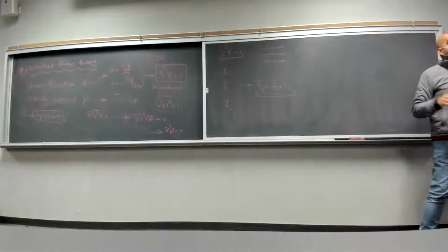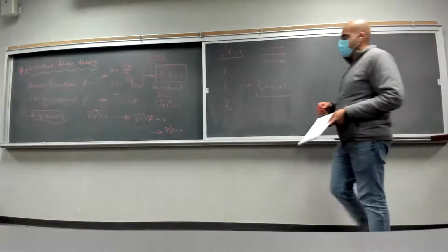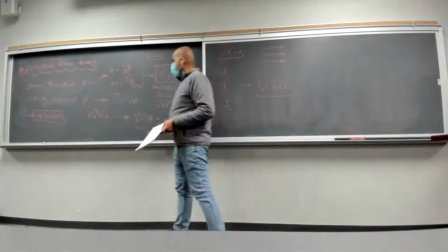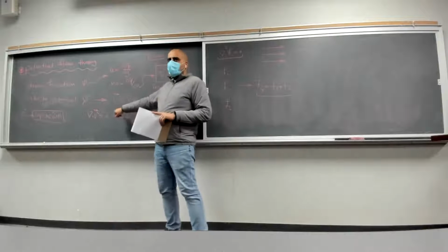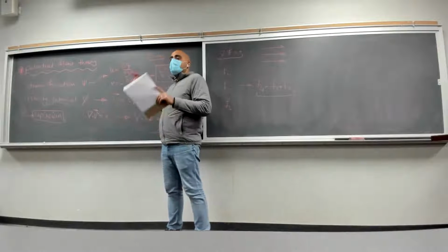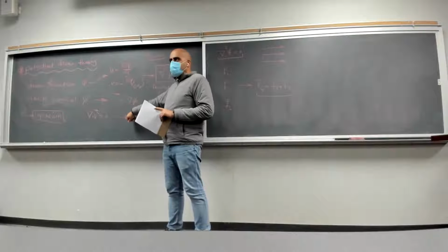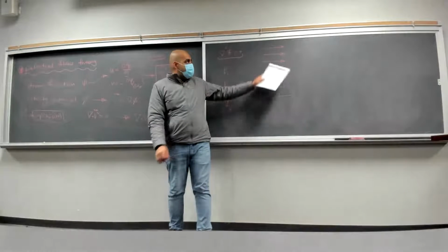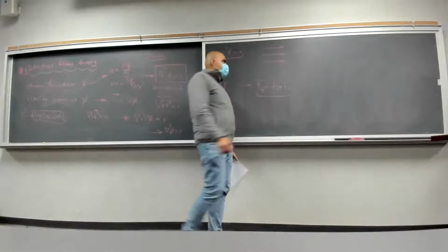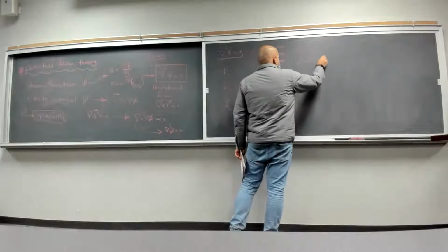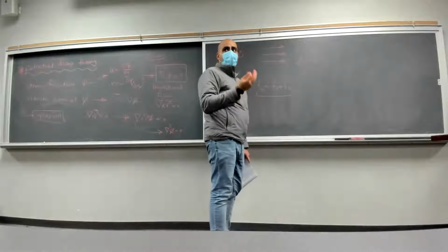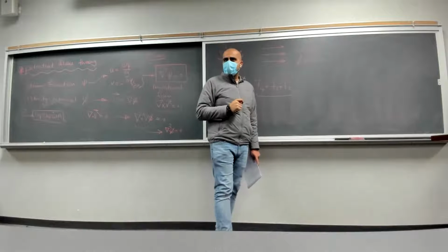And we can also find the velocity potential for this based on this definition. In this case it's a one-dimensional flow, so velocity is the derivative of phi with respect to x. For this uniform flow case, your velocity potential is going to be V infinity multiplied by x. You just have to take the integral of the velocity, right?